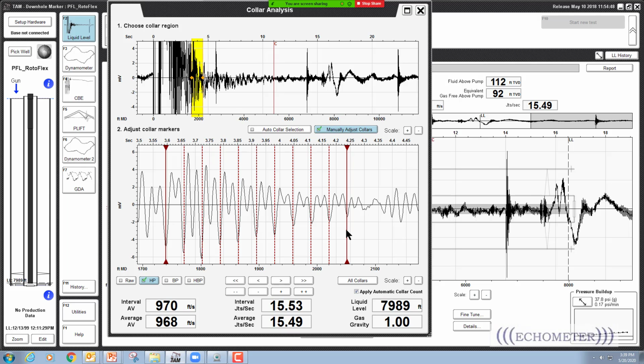What you find is if you plot the height of the stabilized gassy fluid column versus the pressure at the top of the gassy fluid column, that plot is a straight line, and it represents the change in pressure versus change in height. PSI, or pressure change versus height change, is a gradient, and you can actually measure the gradient doing this Walker fluid level depression test.